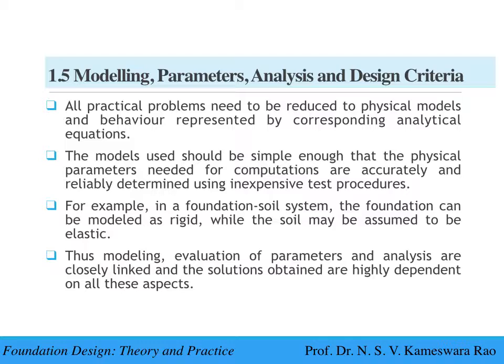All practical problems need to be reduced to physical models and behavior represented by corresponding analytical equations. The physical parameters of the system form the inputs in the mathematical equations for computing the responses. The models used should be simple enough that the physical parameters needed for computations are accurately and reliably determined using inexpensive test procedures. For example, in a foundation soil system, the foundation can be modeled as rigid, while the soil may be assumed to be elastic.